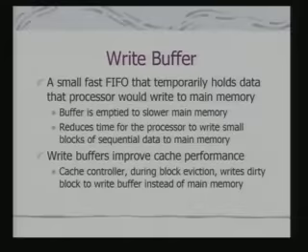So the processor now needs to wait only for the time required to load the data from main memory to the cache, and at the same time data is being streamed in. If I did not have a write buffer, the time taken would have been double when there is a block eviction, because if I consider that access time for read and write is similar, you have to first write back a block, then you have to read the block, and only after that can the processor really start execution. So that time can be reduced by using this write buffer.